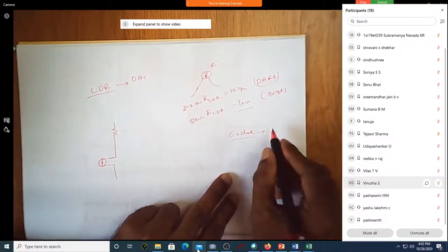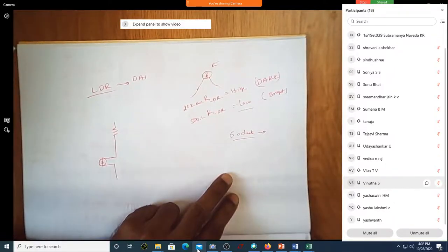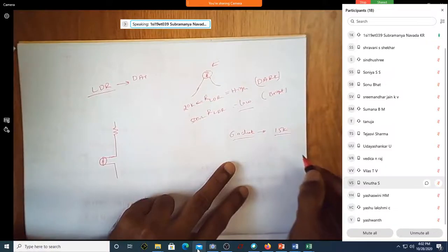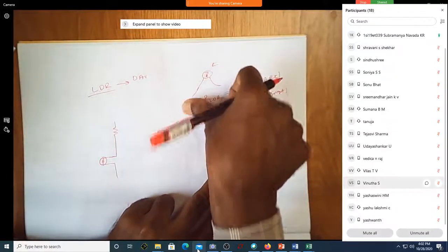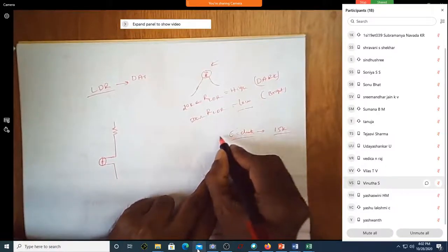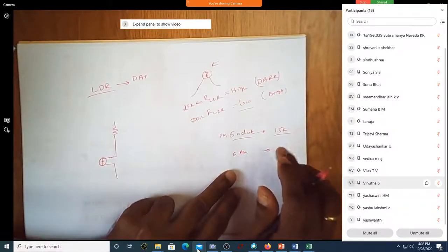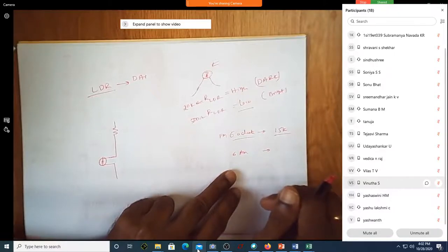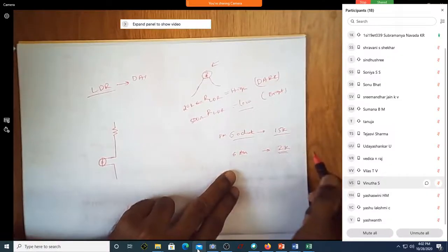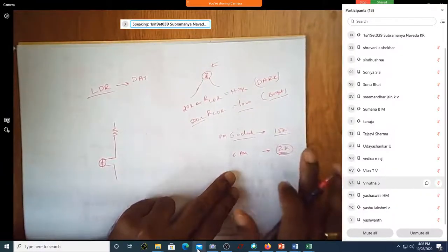So let us take this LDR outside at 6 o'clock. Is it dark now, during this season? Shall I take the resistance as 15 kilo ohm? This is when it is fully closed, though not quite fully closed because there is some light. Again, this is 6 p.m. Now let us take 6 a.m. By that time the sun is almost out. Is the resistance around 2K? Okay, now for bright it is 500 ohm. It is not that bright, but it is light.